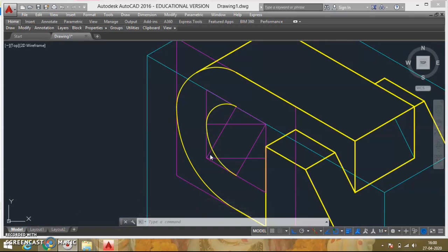So we get this curve. What we did, we have taken this as center and this much as radius, and rotated it. Now next, again we'll do the same thing we did here. We'll take this as center and this much as radius, rotate it. And then you take this as center and this much as radius, and rotate it. So you get that ellipse, the complete ellipse.